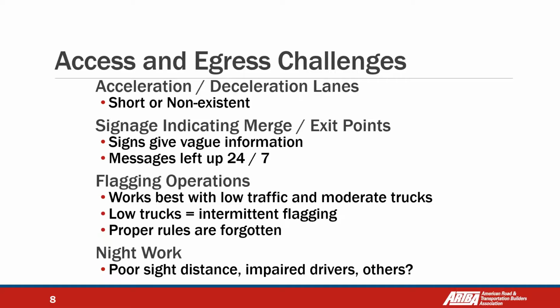So night work, okay? If all these challenges are difficult, they could become worse at night. So high visibility, clear signals, proper lighting for working at night are very important for motorists or operators, workers, and everybody involved in the work zone.